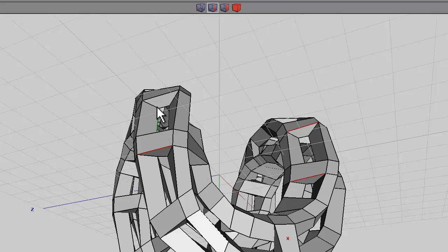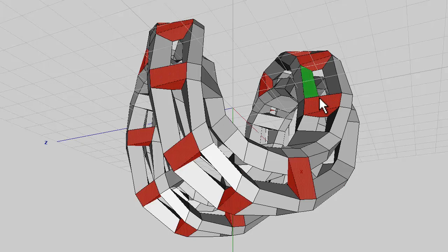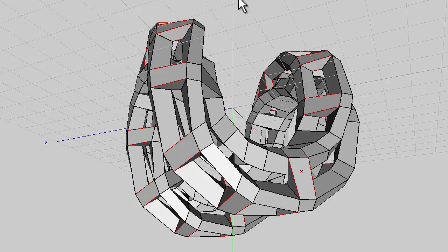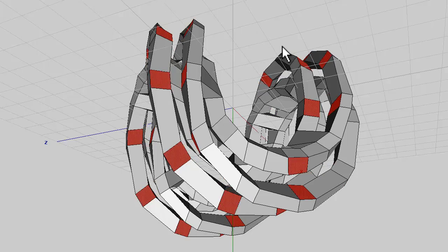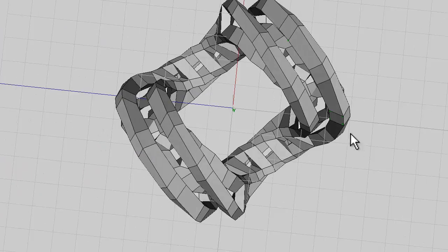So I'll select a few of these and see if I can pick a few off in one go. If I select some of the wrong bits of the geometry there, it's going to set me back. So just pick some of these out, press identical, get faces and delete. Control Z, I must have, need to press G, don't I? Control Z, so Control Alt Z will take me back. G, so I go all the way around the outside. That's it. So I'm just trying to leave these 4 strips.